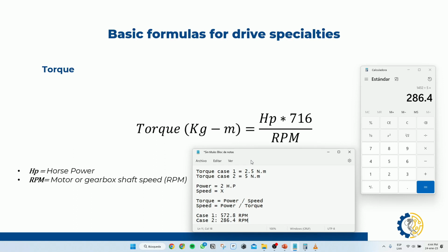Now, guys, this does not happen internally in our drives. You might say, well, if it's that, then I'll just change my frequency from 60 Hertz to, let's say, 5 Hertz, and it should be able to load, right? It doesn't actually work like that with our inverter. All we do is modify our sinusoid waves, which is a PWM, which is going to be modified.